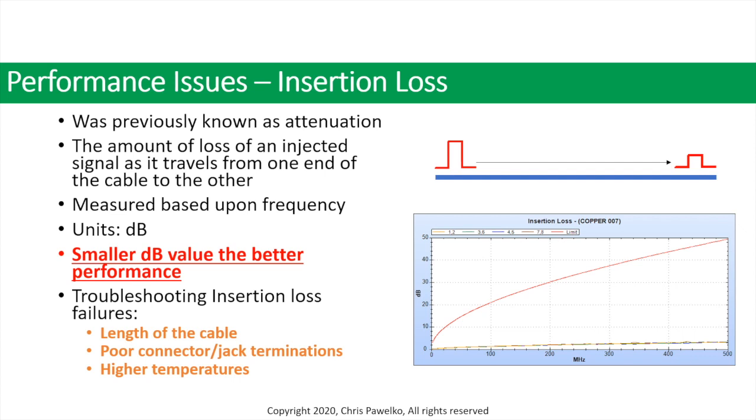And to troubleshoot insertion loss failures, the very first one is length of the cable. If your cable is too long, then it could fail insertion loss. You can also look at port connector and jack terminations. And last but not least, higher temperatures do cause insertion loss in cable.